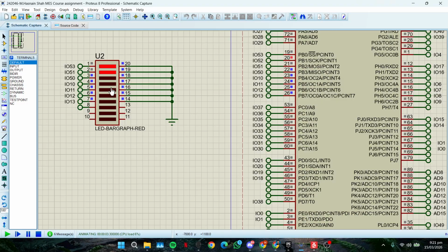So what's happening here? Watch the top LED, the PB0. It represents 2 to the power 0. It toggles on every single count. The second LED is PB1, represents 2 to the power 1 and toggles every 2 counts. The pattern continues down line by line. The time the bottom LED PB7 turns on, you know the counter has reached at least 128. So this is the perfect way to visualize how data increments inside a computer's CPU.